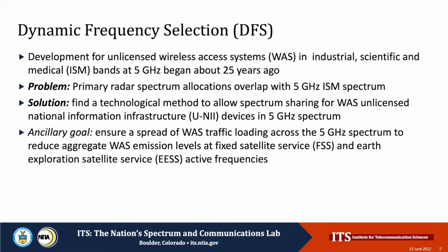National Information Infrastructure, UNII, devices in 5 GHz spectrum, and, along the way, to ensure a spread of WAS traffic loading across the 5 GHz spectrum to reduce aggregate WAS emission levels down to the required levels for fixed satellite service and Earth exploration satellite service, EESS, compatibility.